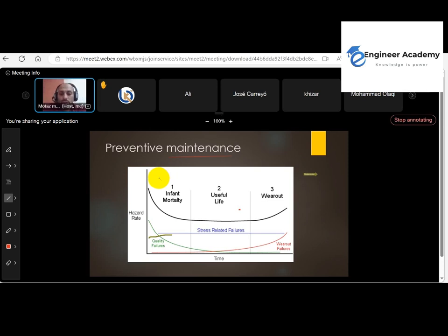After 12,000 running hours, you need to do something like a hot gas path inspection. After 24,000, you have to do the same, maybe a borescope inspection for each 6,000, and also you can do another hot gas path. And after 45 or 50, depending on the turbine type, you need to make a complete or overall maintenance, like replacing a lot of parts.